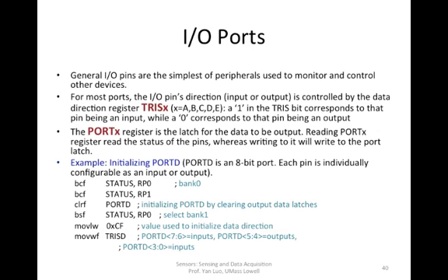Okay, so bit 0 in TRISA corresponds to A0 of your chip. Now, on this TRISA 0 bit, you can have 2 values, 0 or 1, right? If you put a 1, you're going to use this pin as an input. If you put a 0, you're going to use this pin as an output. It's very simple, right? You can picture it. 1 is input, 0 is output. So that's how we're going to use the TRISA register to do that.